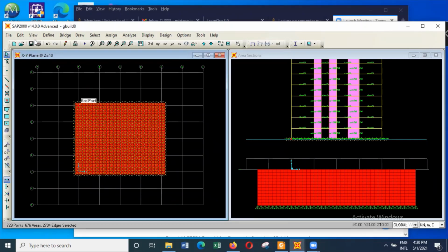And the advantage is that it will remove some soil, and it will compensate for part of the weight of the structure. So we'll say we are going to have either 1.8 meters or 2 meters. I think 2 meters might be easier.